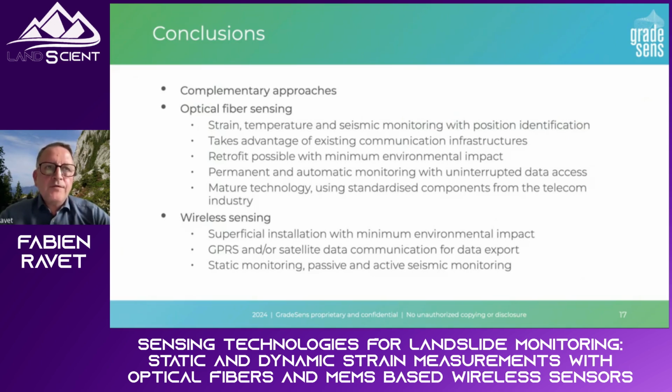If you really want very accurate strain measurement, you may have to do some excavation, but you can take advantage of remediation work to install that specific cable and splice it to the communication cable. And the advantage is that when the equipment is connected, you can hook it to the communication network, take the data, do the analysis, and eventually generate alarms when it's configured for such an application. And really, we get a system that is permanently monitoring the infrastructure and detecting events that can threaten it.